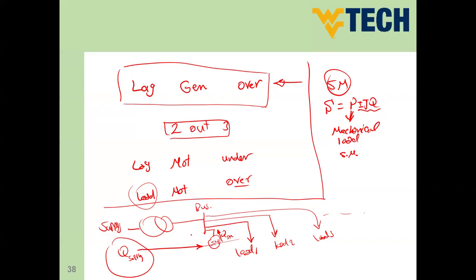This would improve the overall power factor at the bus bar. And you know from electrical circuits, guys, that if you improve the power factor, this will reduce the current absorbed in this cable. This would reduce the stress on the transformer. This would reduce your electricity bill. You will not have penalties because of the power factor. So all of these are benefits.